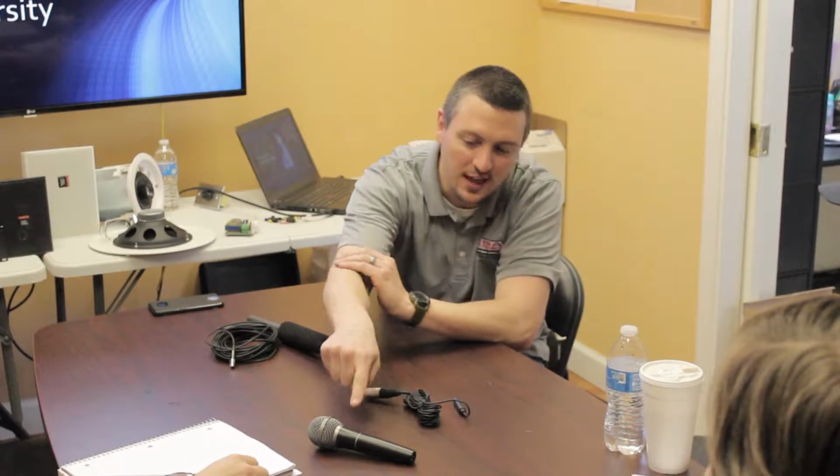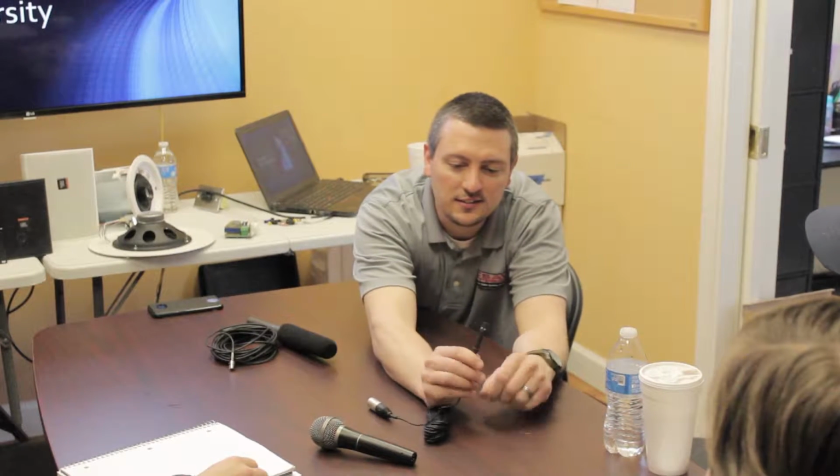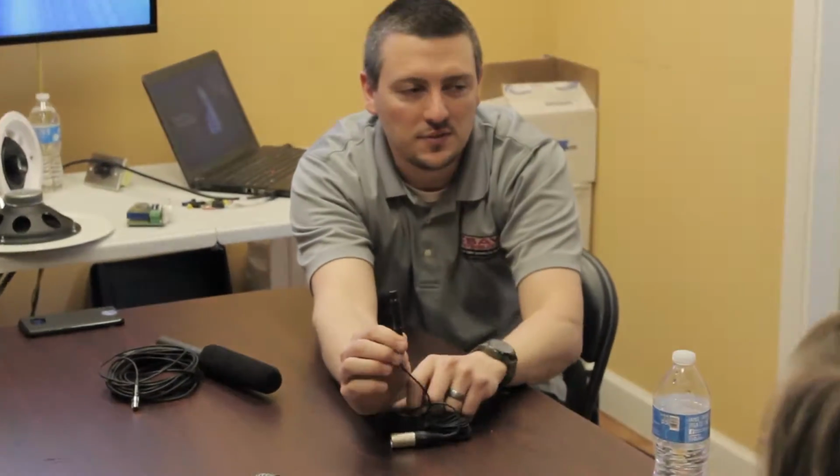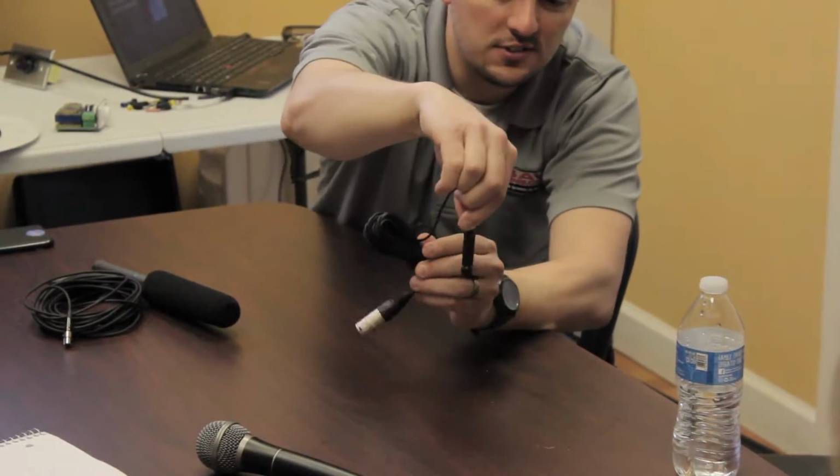So, what's that make of that? Condenser. A condenser mic. What's different about this mic than that mic? Does this need anything special? 48-volt phantom power. Right. Do you know what kind of pickup pattern that is? It's like a ball, right? This isn't omni. This is cardioid? Cardioid. Yeah. So it actually has the same heart-like pattern that he was describing, although it looks like a heart when it's upside down.